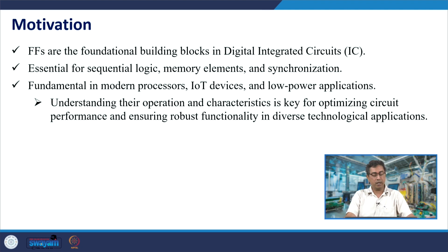Flip flops are used in both synchronous as well as asynchronous circuit design methods. Flip flops are one of the fundamental circuit elements which help synchronize the signal flow, and their operation becomes very critical and very challenging in the near threshold voltage domain. That is why we are specially discussing flip flops in a detailed manner.